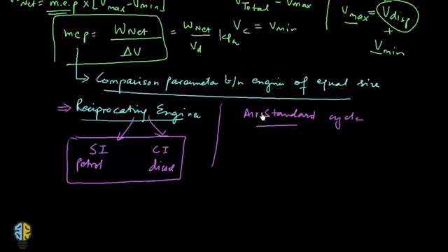Alright. Now to simplify the analysis of IC engines, we make use of air standard cycles. So air standard cycles are conceived, and in an air standard cycle, a certain mass of air operates in a complete thermodynamic cycle, where heat is added and rejected with external heat reservoirs, and all the processes in this cycle are reversible. So it's basically an idealization of the actual processes that are going on inside a reciprocating internal combustion engine, because in actuality the complete engine is non-cyclic.